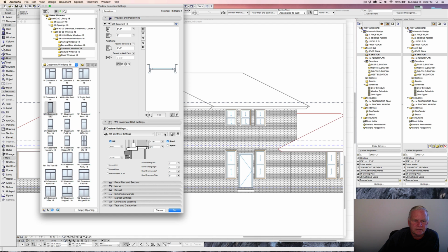Move on to the next, sill and stool settings. So we're going to set the sill to 3 degrees, just to have a slight pitch on that. The overhang of that wood sill is 1.5 inches. Inside it's 1 5/8 inches, 3/4 inch thick sill piece. And I'm going to click, I do want an apron, and that apron is preset for 1/2 by 2. If you're clicking along on yours and they're different, make them the same, change them, do whatever, just so you can see what it's looking like.